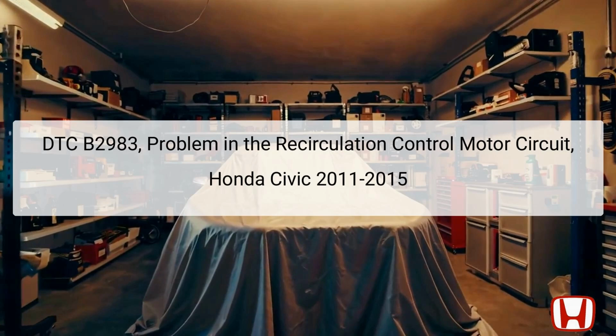The DTC or Diagnostic Trouble Code B2983, also known as DTC Indicator 57, indicates a problem in the recirculation control motor circuit, linkage, door, or motor in Honda Civic models from 2011 to 2015. This vehicle is equipped with a climate control system that includes a recirculation control motor, which regulates the flow of air into the cabin by controlling air recirculation. This motor's failure can lead to improper climate control operation or reduced air quality inside the vehicle.